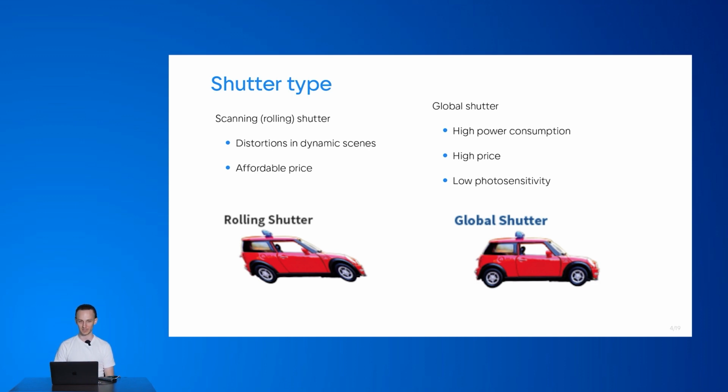And in such a dynamic application as robotic football or any kind of dynamic robotics or autonomous robotics, with these types of applications, we usually have to have all our lines straight. So in robotic football, it's better to have the global shutter type cameras instead of rolling type cameras. The consequence of that is the dramatic increase in the price of the cameras. They tend to be, so to say, industrial grade cameras, so they cost a lot. And another thing about them is that they can consume more power than regular rolling shutter cameras.